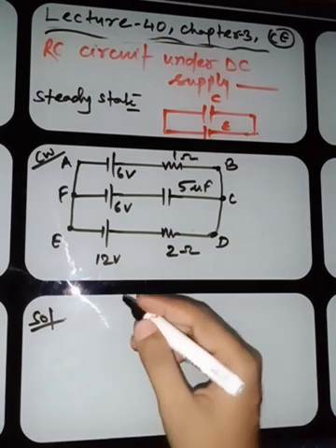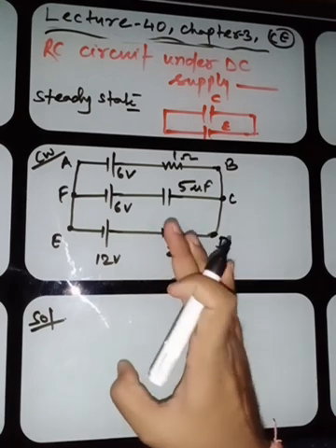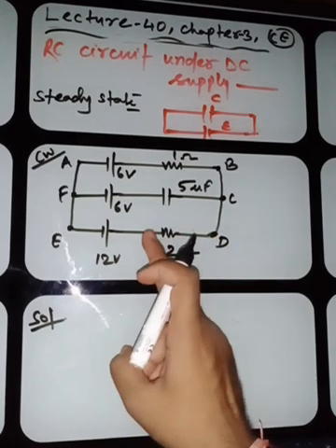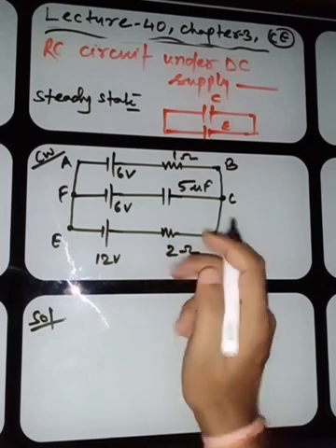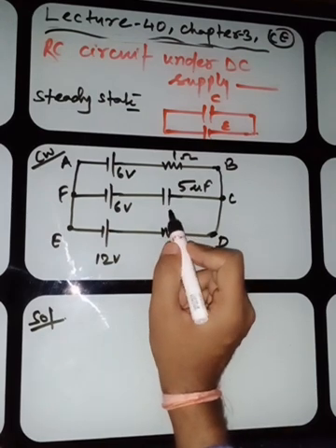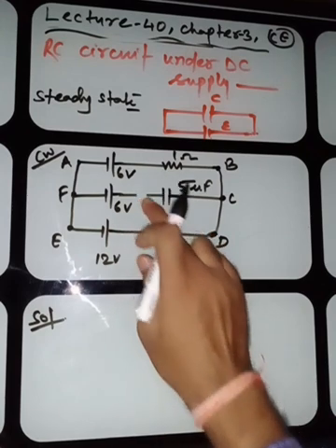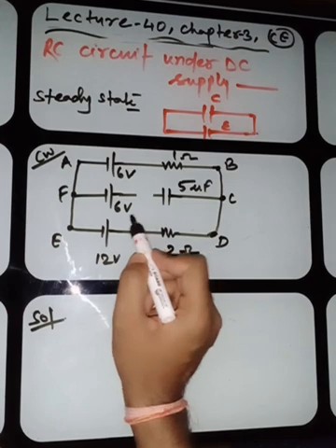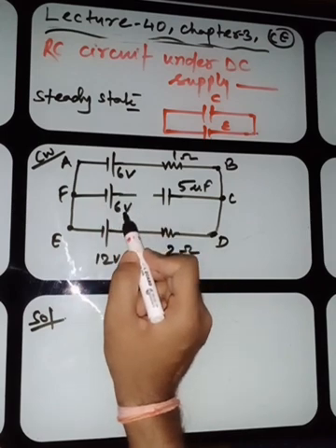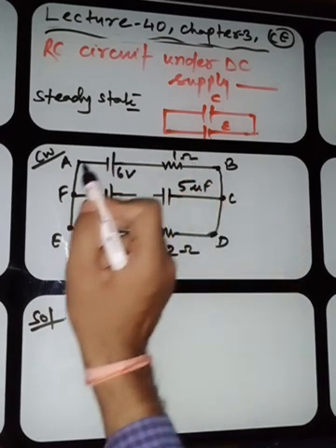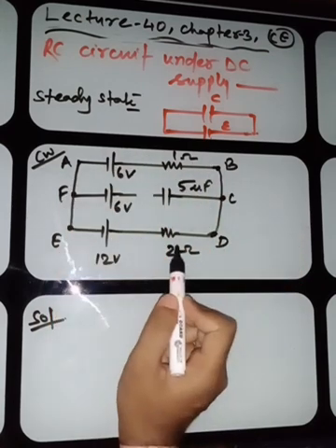First, we have to find the equivalent resistance and total current flowing through the circuit. Now, if this particular capacitor is connected in the circuit and this is considered an open circuit, if it is open from anywhere, it means this particular battery will not provide any current in the entire circuit, remember.